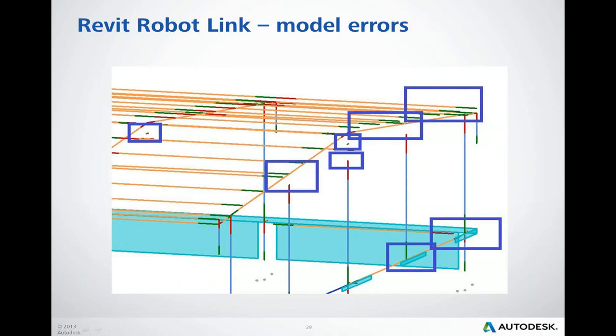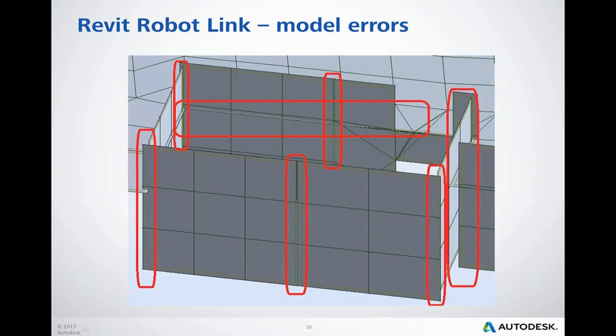Now a few slides with typical Revit analytical model errors. Paying less attention to the analytical model and model accuracy may result in situations like this. Beams, bars, columns not connected to each other. Similar things happen with walls. Accuracy. Revit walls in Robot, as you may see. Wall and slab analytical edges are not lying in the correct planes, so they are crossing other walls rather than meeting them in the proper plane.